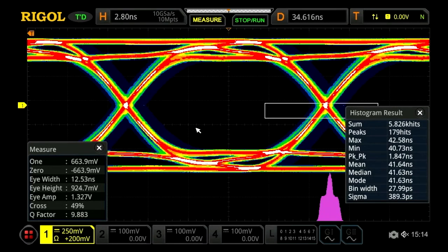The first problem we found was the signal that was causing the amplitude noise. So we've been able to remove that, isolate that crosstalk, get rid of it, and reduce our noise on all of these signals. So now we can see how these signals are separated, the top layers, and we're starting to open the eye a little bit.